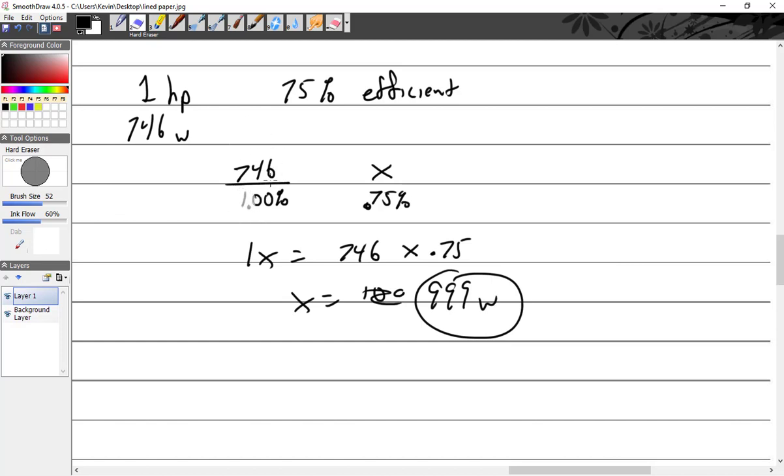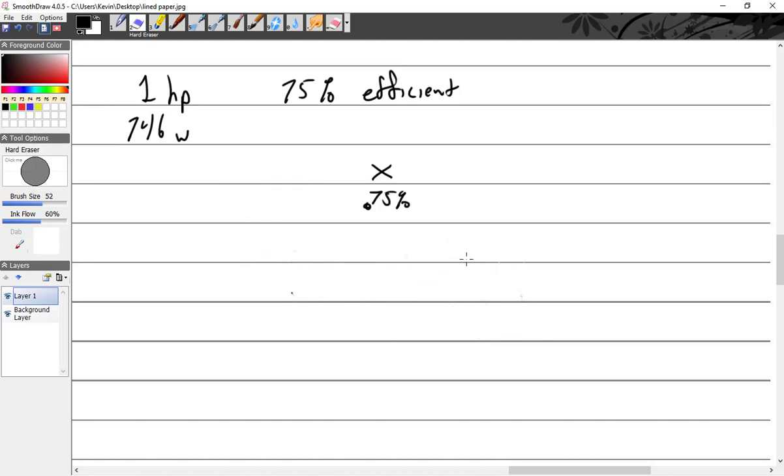How do you know it's not 75% of 1 horsepower, or that it's running at 75%? It says the output is 1 horsepower. That's all. That's the output. The data plate is what the output is. How much does it take in? So is that always the output? Yes, data plates are always output, as far as I know, never what it's drawing. So we have to figure out what it's drawing. Gotcha. So it's going to be 75% more.